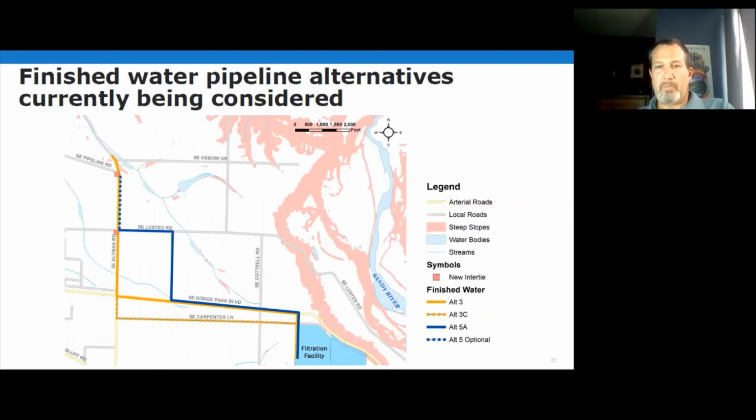Mike. Yeah, about Carpenter Lane. When you said you're putting the pipe in, you need at least 70 feet. So they can do it in narrower. I think on the Washington County piece, they went down as narrow as 30 feet. The narrower it is, the longer it takes, because they're more restricted, and which consequently makes it more expensive because they're getting less production per day. So they can do it in narrower. The most efficient width for them is close to 70 feet, between 60 and 70 feet.